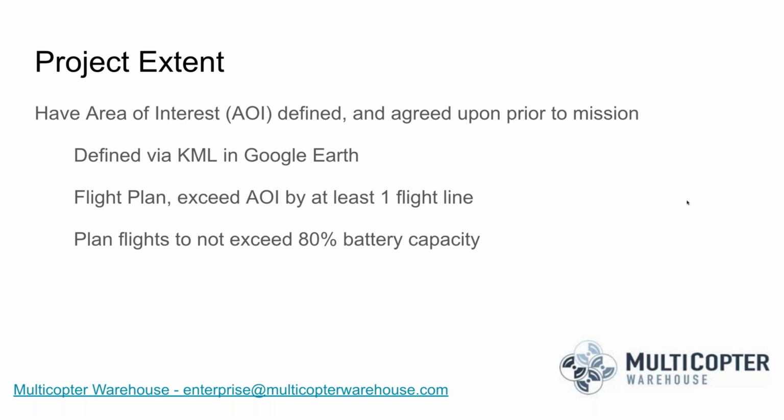And then the last thing you really want to make sure you have well laid out and determined between you and your client is what is the area of interest, or the area to be expected to be mapped on the ground. And a key thing for that whenever you're mapping a project with Pix4D is we always encourage that you map slightly in excess by at least one flight line the area that you're trying to map.